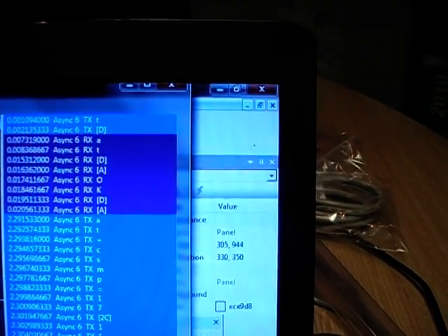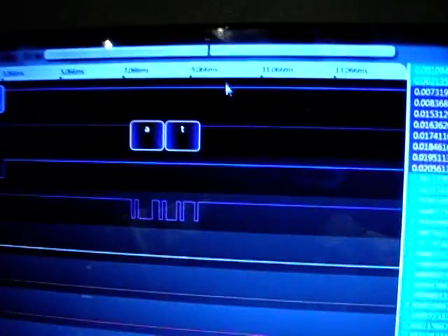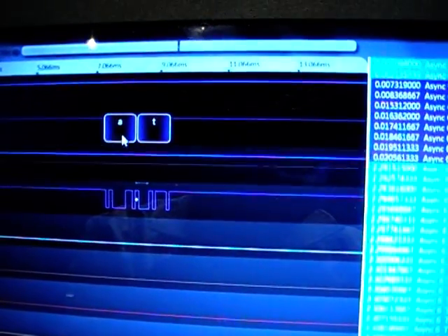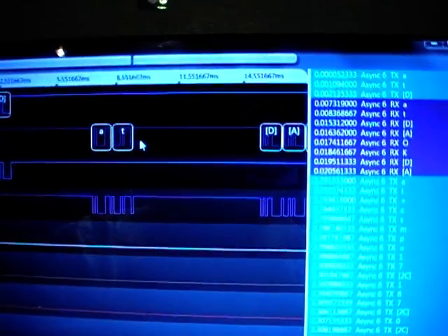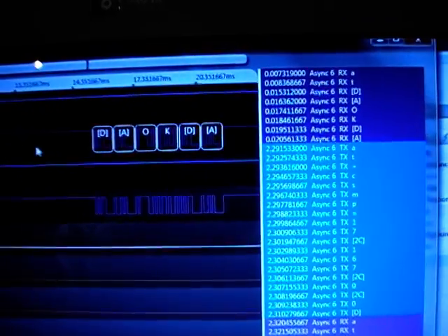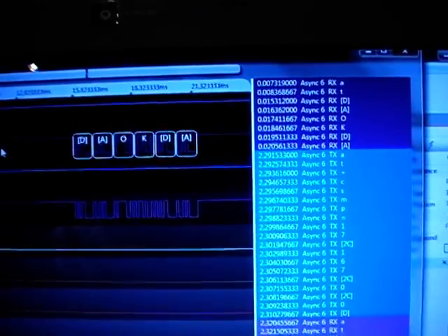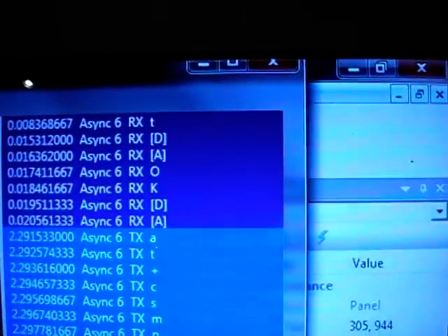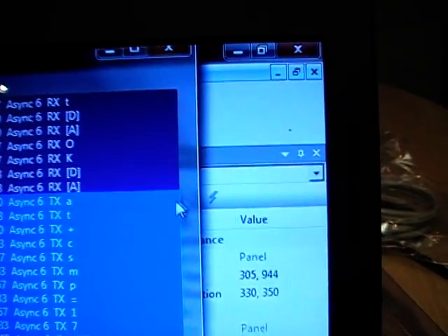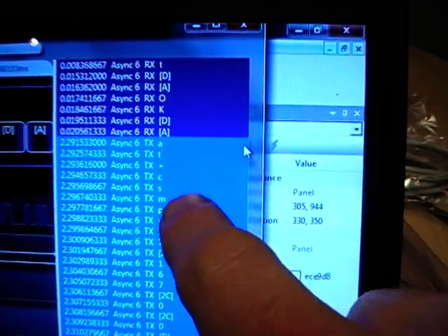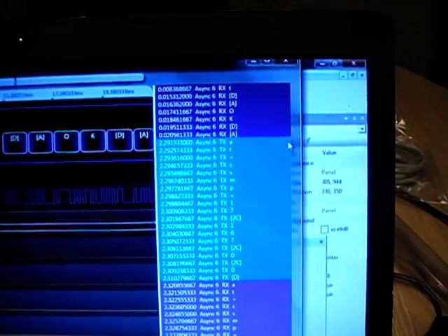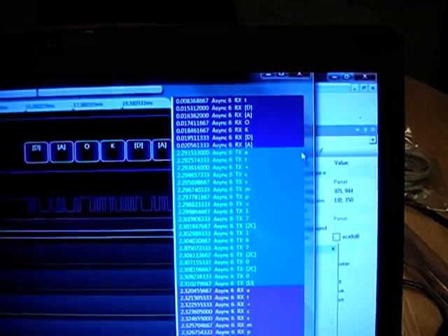So here you can see the RS-232 lines, you can see their ASCII equivalent, or the decoding of the RS-232 lines, and you can see the sequential bits that have gone onto this bus. And there on the right hand side you can see the different commands. So here you can see part of it is AT plus CSM, and actually sending text messages with AT commands is relatively complicated, much more complicated than making a simple phone call.